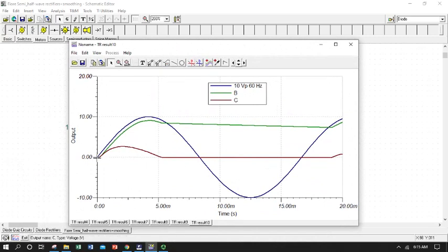So we turned on our circuit and we supplied the first half cycle of our signal out of our pseudo transformer secondary with our voltage source. It came up and it started charging the capacitor. We can see that with our plot C, and at the same time it was supplying voltage to the load, so it was supplying to two things. So our secondary was opening our diode, and then we flowed current and piled up some charge on our capacitor, which we can see with this red plot, and we supplied current to the load. And so we had a voltage drop over the load that traced the input just like we wanted it.